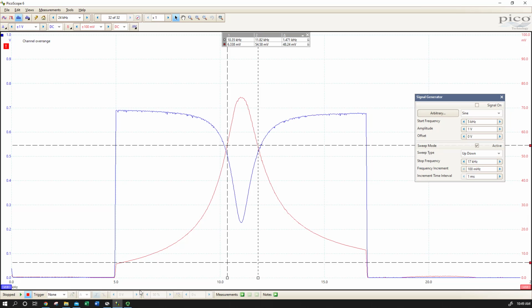Then we went to our spectrum analyzer. We swept the frequencies over a range that started well below and went to well above resonance. And so we were able to look at the frequency response of our circuit, different parts of our circuit, namely the whole thing versus just the resistor, and get an idea of how sharp our resonance peak or trough was. And of course, that bandwidth is related to what's known as the Q factor.